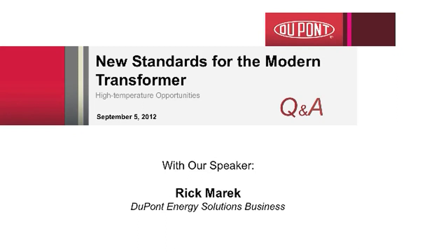Dielectric is a difficult one because the dielectric strength seems to hold all the way to nearly total degradation. So it's not necessarily a very good way to measure end of life, although it is the only practical method for an enamel.